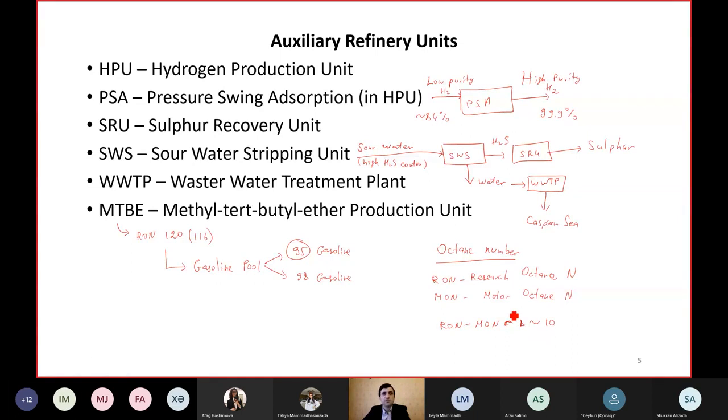For instance, in Azerbaijan, at the petroleum stations, you see RON 92 or 95. But if MON is written, then that would be 82, 85. In the USA, it is written as RON plus MON divided by 2. Is that the answer to your question? Yes, thank you. I hadn't known until now what it means at the stations, but now I understand. Thank you. You are welcome.